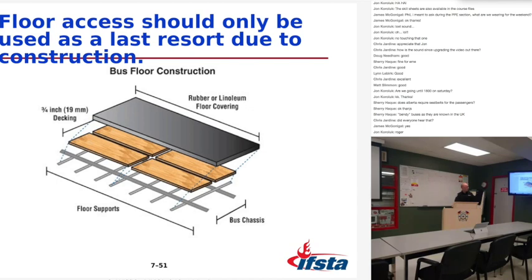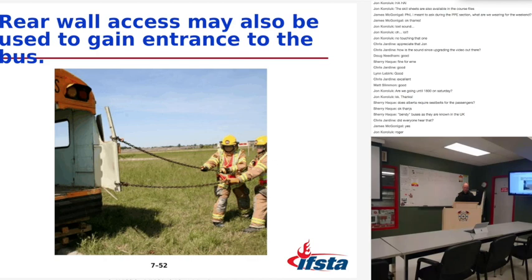So this floor is strong too. So only as a last resort to go through the floor. Inverted fuel tank presents high risk of flash fire when cutting. Transit and commercial buses, you'd have to go through 2 floors because you'd have to go through that storage compartment first.